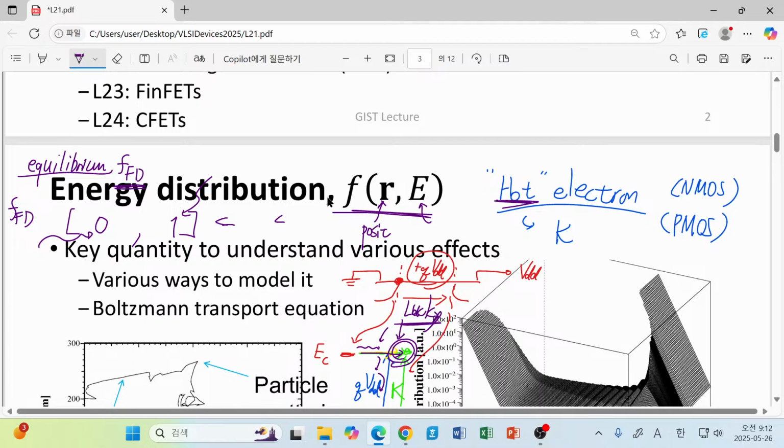So now at a certain position, we can define a different distribution function. Please note that the Fermi-Dirac distribution is not a function of position. It was a sole function of only energy level, once the Fermi level is fixed. This is a global quantity. However, now we introduce a localized, position-wise quantity.